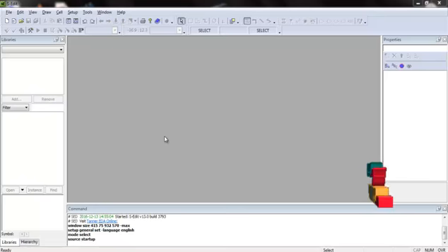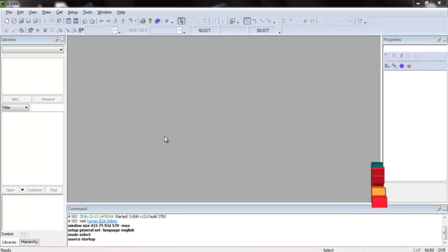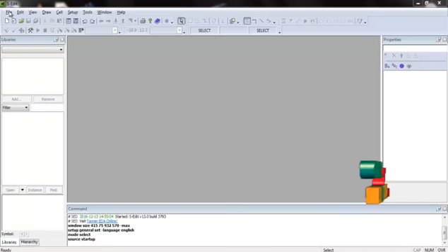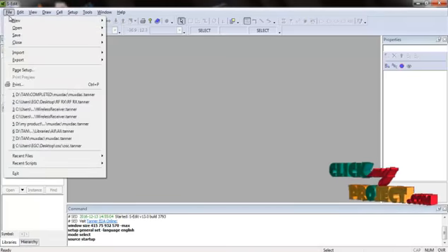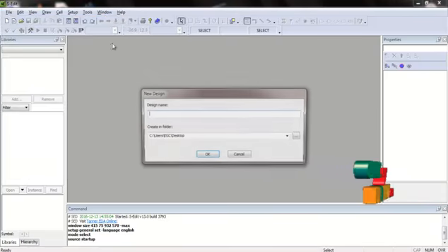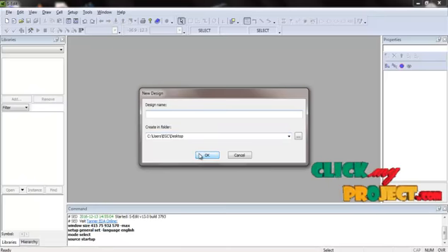Now we are going to discuss the running procedure of our product. In our product we are using the Tanner EDA tool for simulation. First we create a new design using the file option: File, New to create a new design. Assign the design name in the desired path. After assigning the design name, click OK.